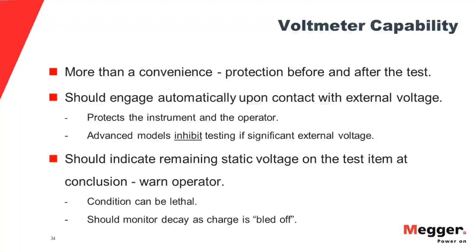Well, suppose he forgets to do that. So we'll talk a little bit about that, because it's extremely important in terms of safety. And if you're ever dealing with new hires, apprentice electricians whose first day on a job it is or something like that, always make sure that they know about the discharge function on an insulation tester.